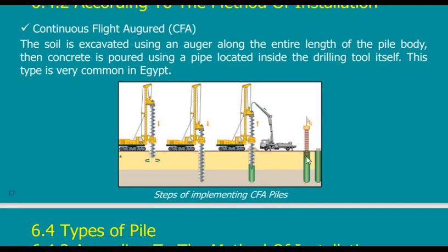But as we said here, the problem is trying to push this reinforcement into very dense concrete, and you need to push it exactly vertically. If it is shifted just 1 or 2 degrees, the reinforcement will touch the sides of the hole, and you will not be able to move it later. So usually we push this cage till I reach maybe 4 or 5 meters, and I find that I cannot move any more.